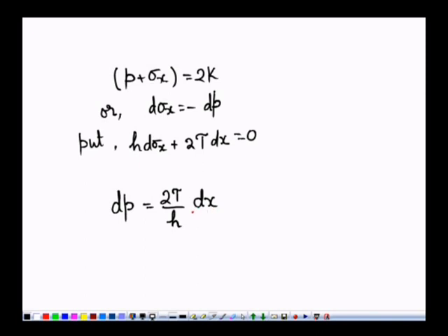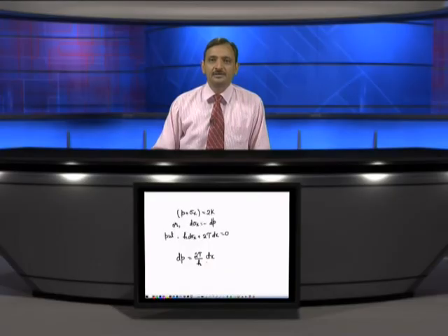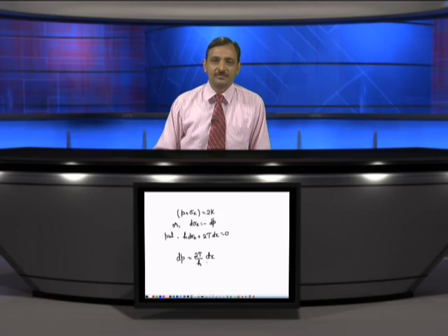So up to now, what we have discussed is that we have taken our workpiece in between the two platens or two dies. We have done the analysis for the small dx strip. There, whatever the shear stress is, we have considered that, and the force applied from the top. During our analysis we have taken the plane type.